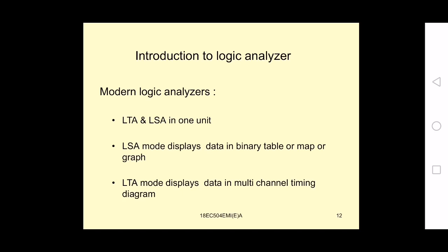In LSA, logic state analyzer mode, the data is displayed in either binary table, map or graph, whereas logic timing analyzer mode displays the data in a multi-channel timing diagram. So modern logic analyzers combine the features of both logic state analyzers and logic timing analyzers into one unit.